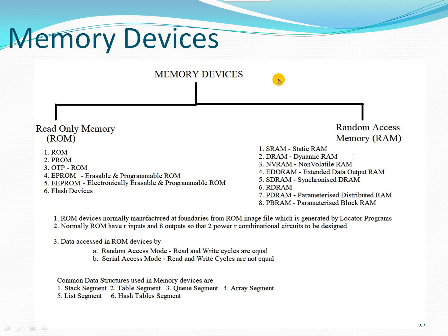For OTP ROM, whenever the design of the embedded system is fixed, the initialization programs and the startup and specialization programs can be programmed in an OTP, because OTP means one-time programmable ROM.